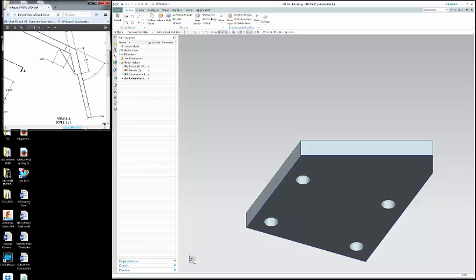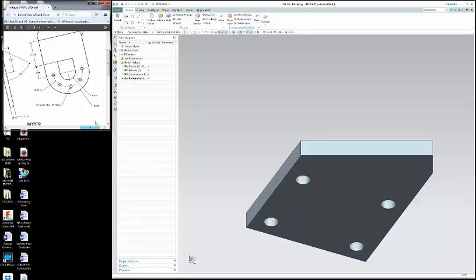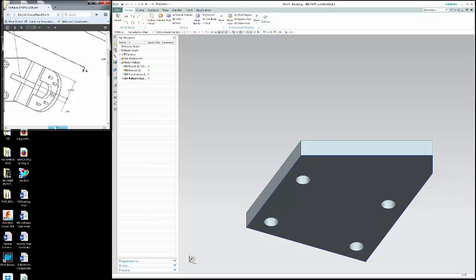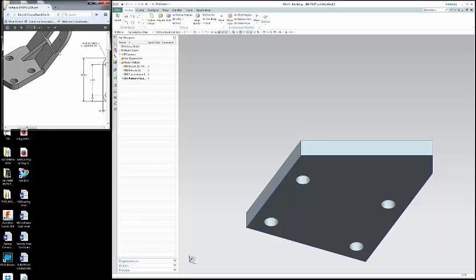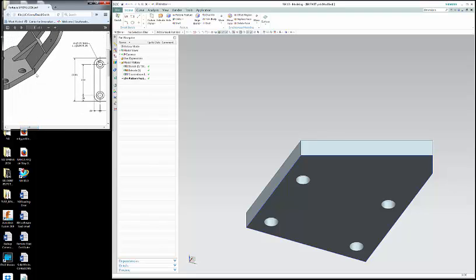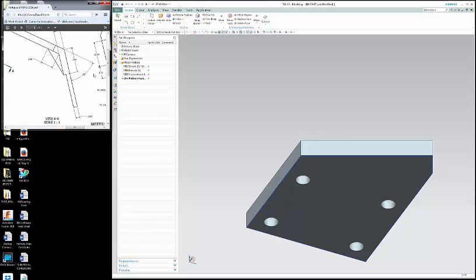Okay, so on the third lab, what we're going to do is try to create this shape right here, which is actually this area right here, that plane, if you will. So all of this right in here. And to do that, we're going to have to create a sketch plane that's coming off of the bottom. And it comes off at 52 degrees off that bottom axis.